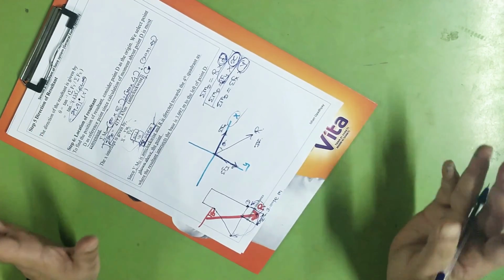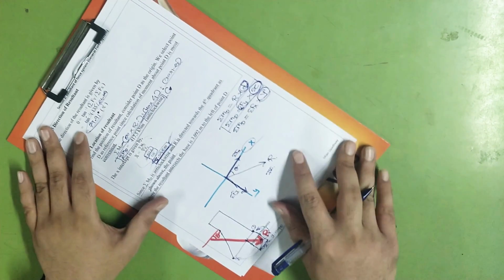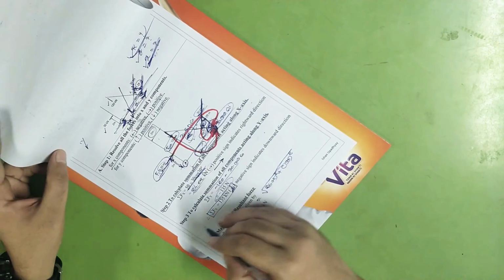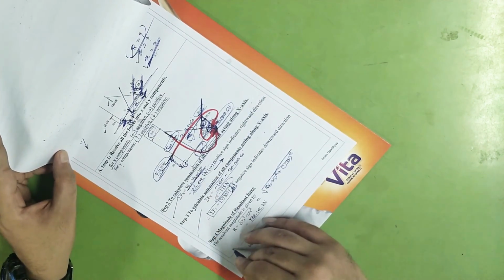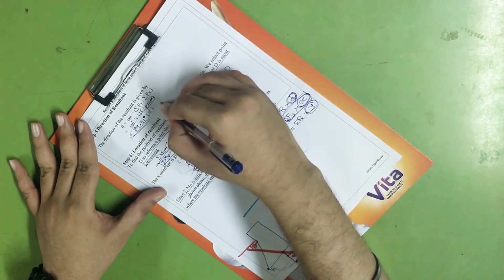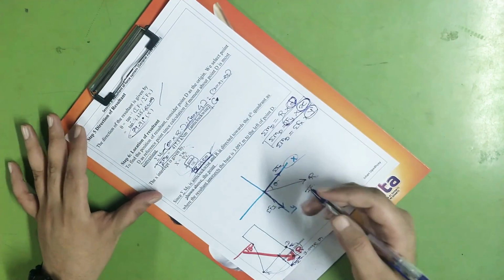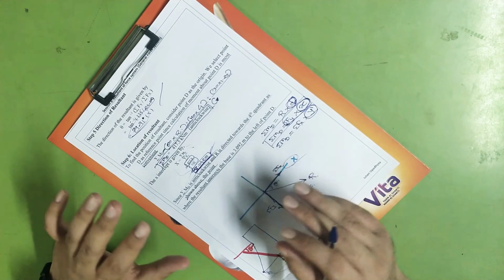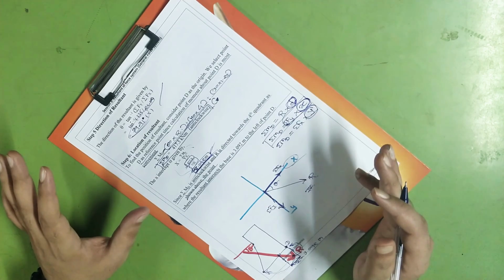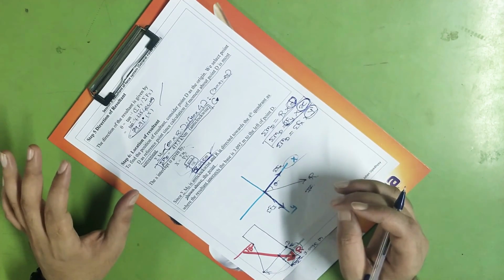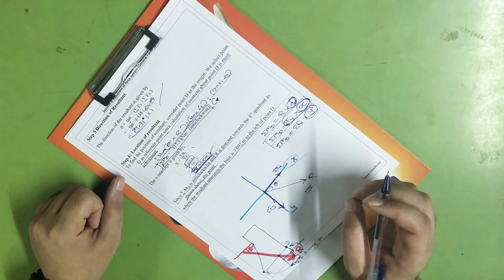3.092 meters. So in this sum, first we calculated the x components, y components, then the resultant, then theta, and finally we located the resultant along its x-axis, that is, where the resultant intersects the base. I hope you have understood this sum. Thank you.